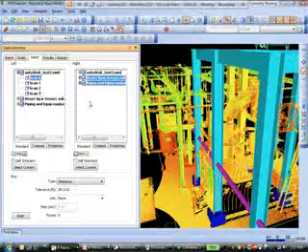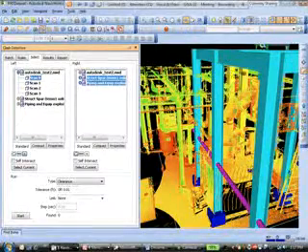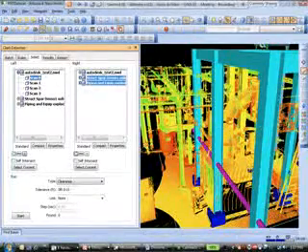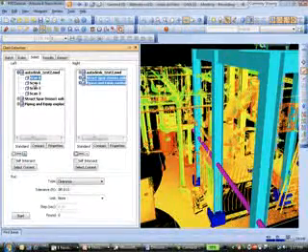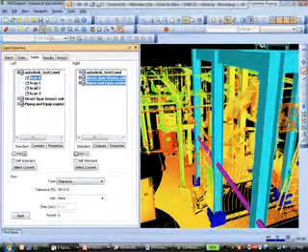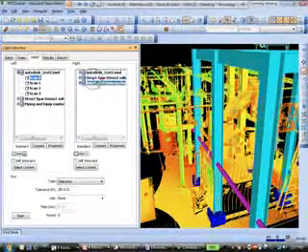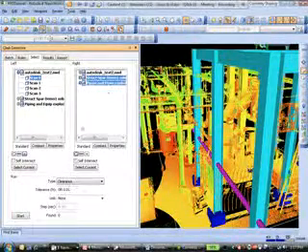So for this iteration, I want to make sure that these new components that I've introduced in here, you can see the structural members as well as some of the piping, are not going to interfere with any of our existing conditions here. So on the left side, I'm going to select Scan 1. I'm just going to take one of these initial scans at first. Now remember, there's 4 different scans that we can choose from. But if I use just the initial one, then for the right side, I'm going to select our new components, our structural components, piping.